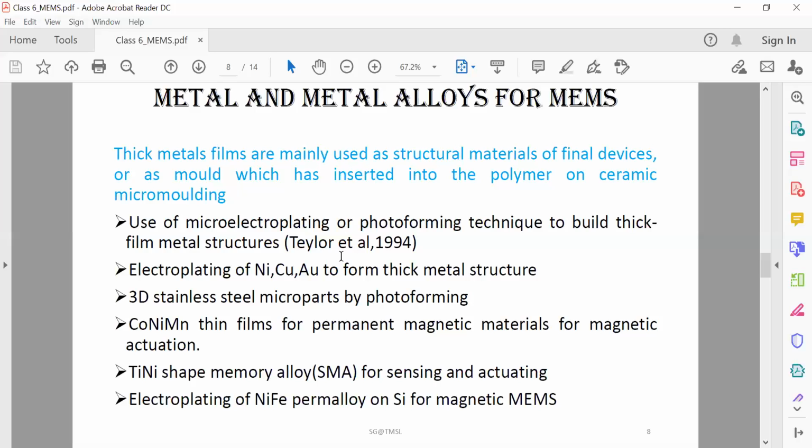Conventional techniques used for VLSI metallization are mainly thin film evaporation. But copper cannot be evaporated in vacuum by resistive or electron beam evaporation, which is basically not possible. So electroplating is the only choice by which you can get the copper film on silicon or silicon dioxide, used for VLSI interconnection.